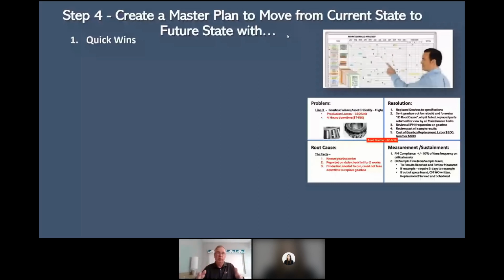Like one organization right now, they've got a lot of air leaks in their plant, and what we're going after are the air leaks. Why? Because they're running 4 compressors. What they ultimately find out once they repair all those leaks with a contractor, don't try to do it yourself, don't use your maintenance guys to do it, get piping contractors, is they'll go from 4 compressors to 2 compressors. I bet money on it.